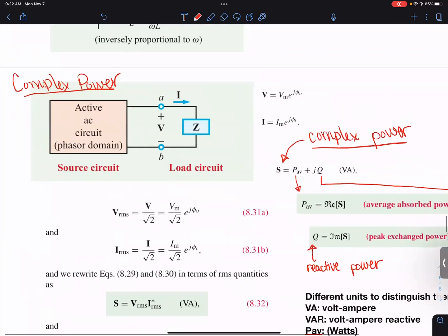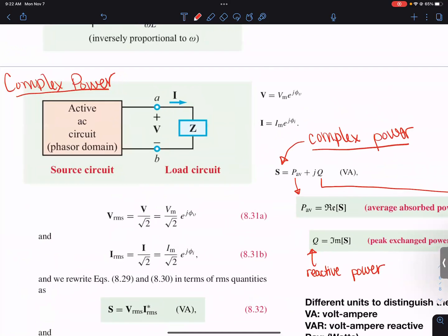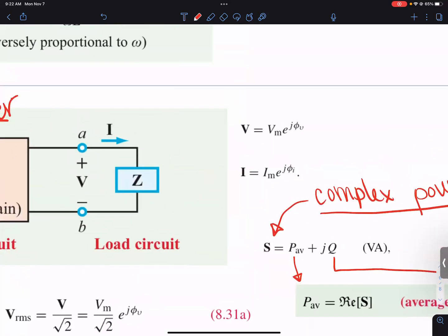So now we can go back to the complex power with that understanding. And with the complex power, if we look at writing them in the polar coordinates of that VM, which is our magnitude, remember our v of t was VM cosine 377t minus some shift or plus some shift. So that shift of V, and then the I had the shift of I, so theta I.